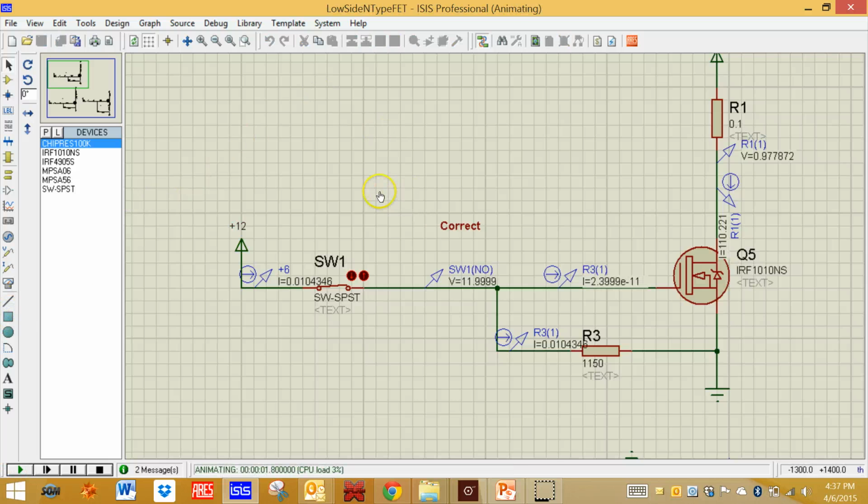And again, this is 12 volts on the gate, so it should be smacked well. But still, your voltage is 0.97, right? Your current is 110. It's getting a little closer. It's not a perfect switch. You're losing about a volt drop across that. The amount of power that's being dissipated is 0.97. That's close to 1. Let's call it 1. 1 times 110, you're burning up 110 watts in this FET. So you better get it cool, or else you're in deep trouble.